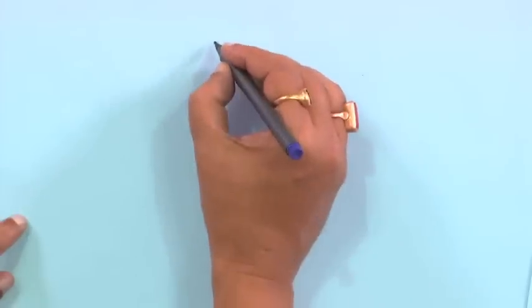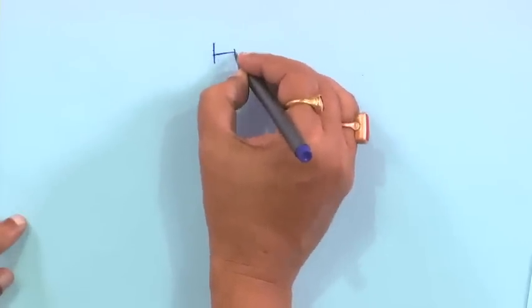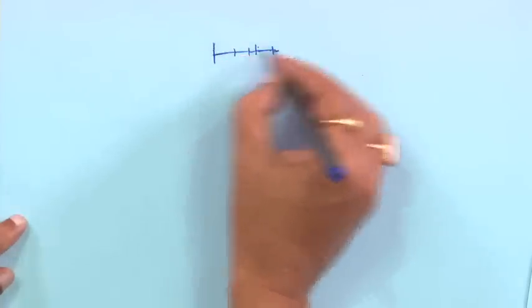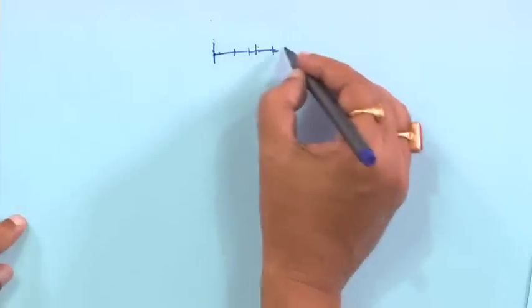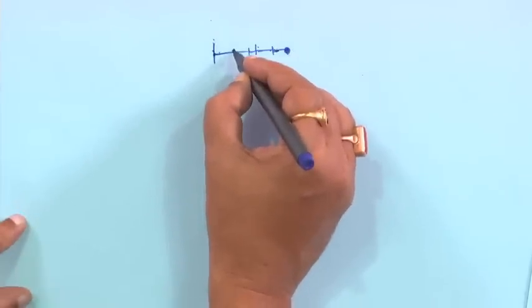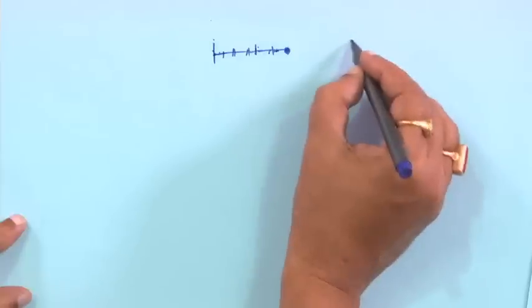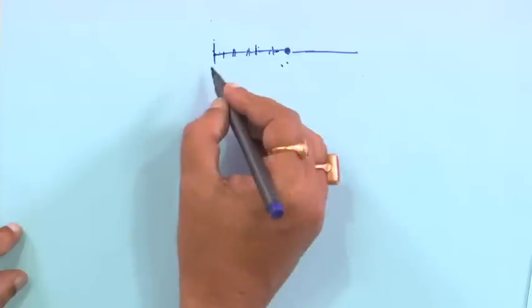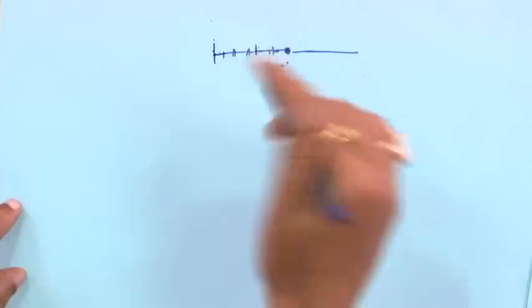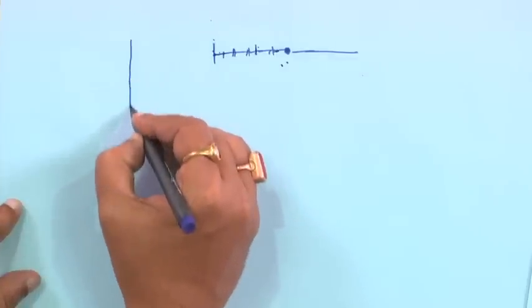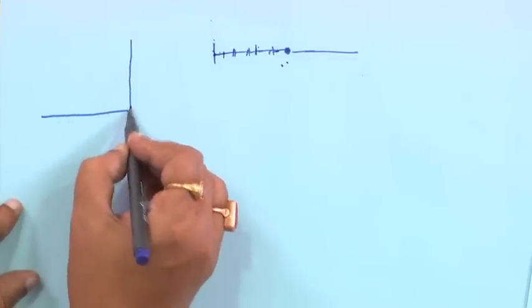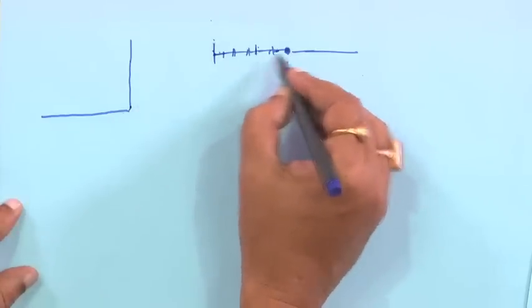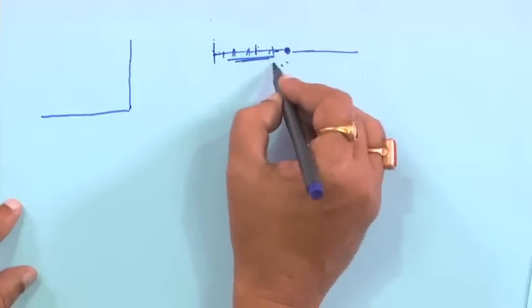You can observe that suppose this is the line. So, this is the insulator string, and it is coming like this. This is the cross arm, it is connected, and suppose the conductor is connected here. You can see these are all the insulator pieces. The conductor is coming from somewhere, and horizontally it is placed as a tension string. When a line is coming from one direction and takes another direction, any angle direction, then at that point it will be your tension type, kept in a horizontal position.